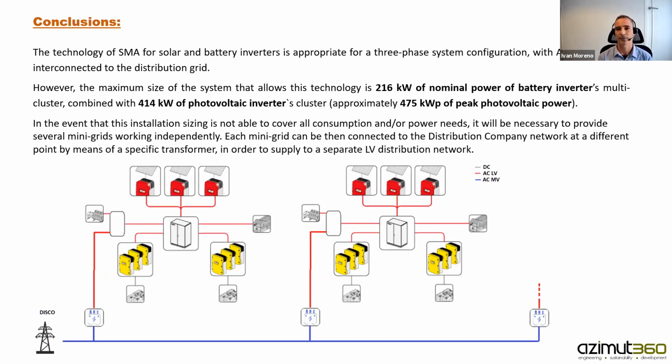It's very optimum. If I may also add one point, from the experience that we have on the ground, systems up to the size that you have just mentioned are mostly at the maximum size that you can have in a low voltage distribution network. So from that point, this limit is actually not so bad. It covers pretty much what you can do with a low voltage network as well. Okay, many thanks, Imran. That's a good point.